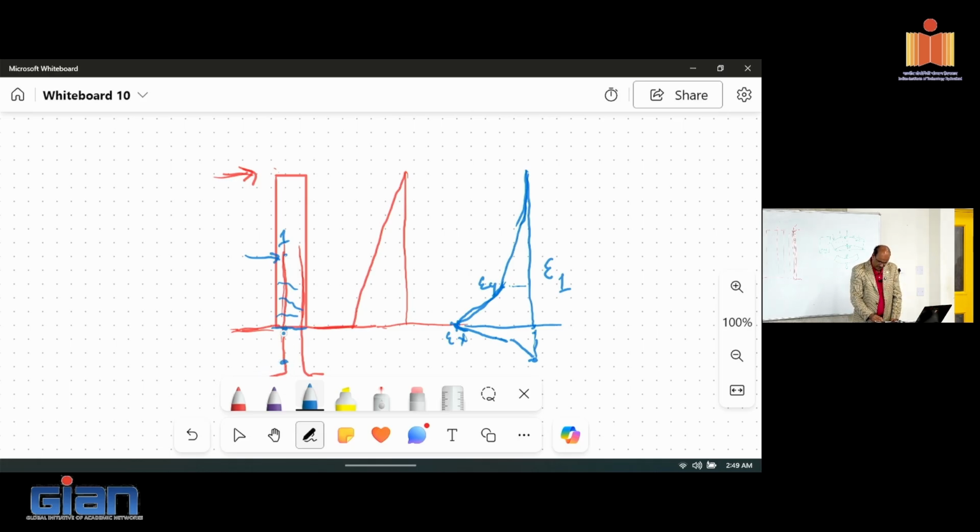The reason we leave all of this space, including the 90-degree hook, is to bring the strain back to 0. At this point, regardless of whether you allowed adequate length or not, the strain is 0. Often people ignore the fact that strain actually penetrates into the adjoining member or element, right? That's an important piece, known as strain penetration.